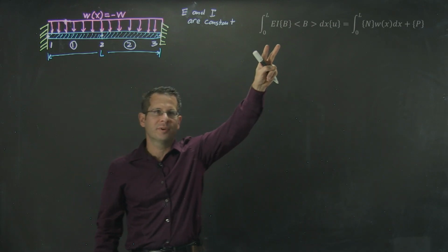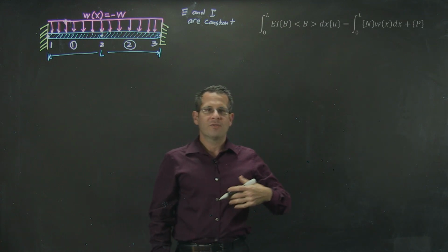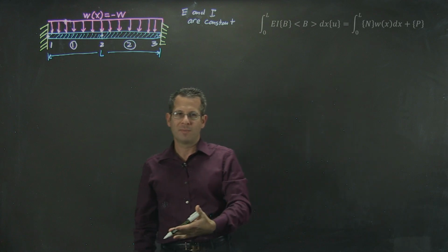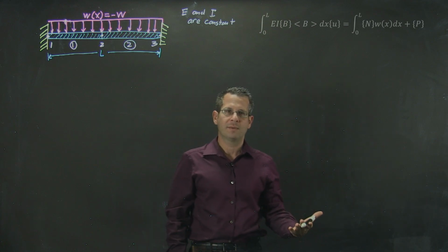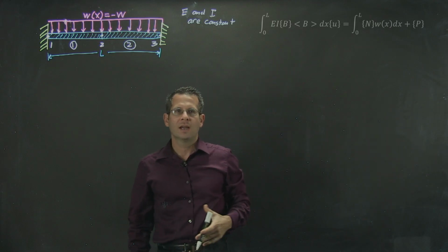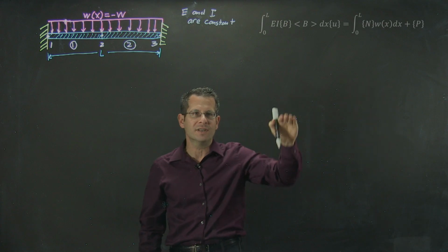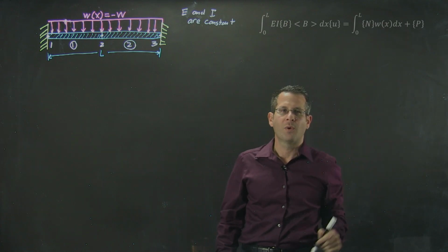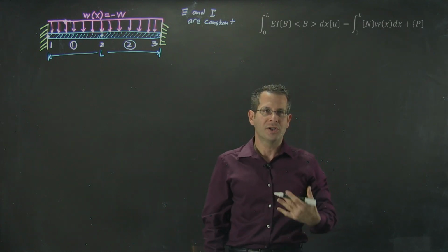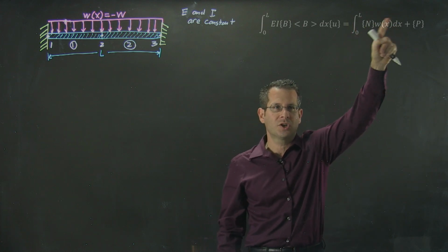This linear algebra equation here. The only reason for the principle of minimum potential energy method or the Galerkin's method was to arrive at this formula. This is the formula I will use for all of my beam problems. I can even use this formula for a beam problem without a distributed load. I would just say W of x is 0, so therefore this term is 0.